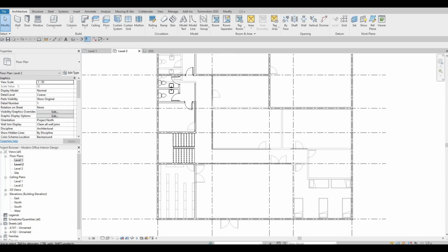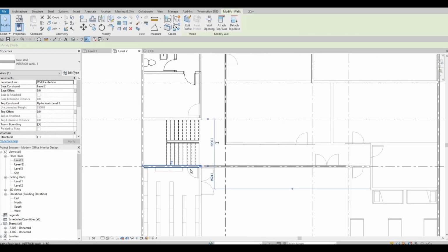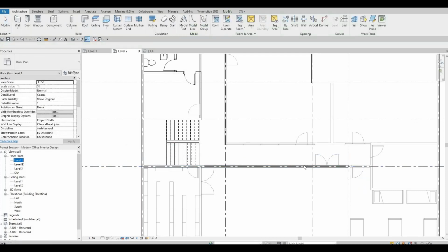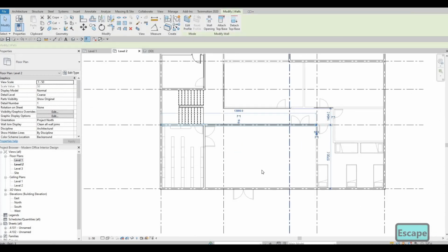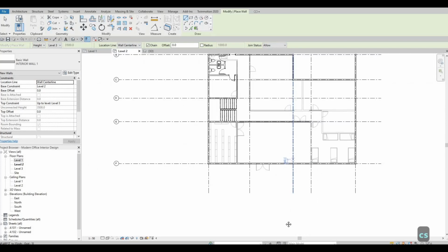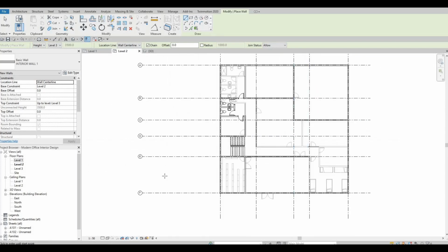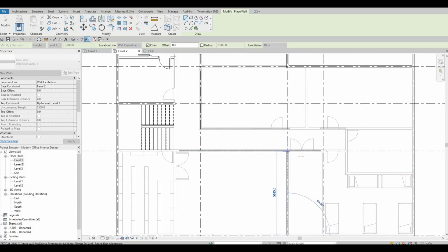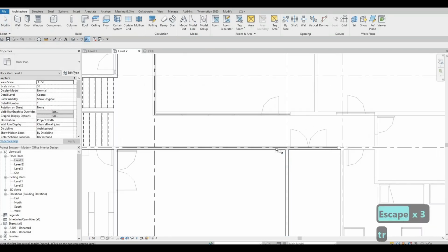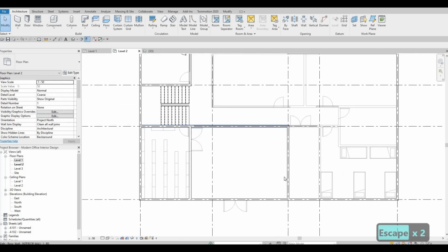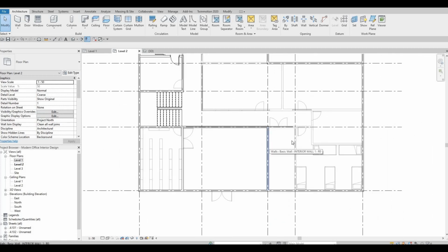Also, what we're going to do is select this interior wall, and I want to extend this all the way right here. So just extend that, select this interior wall again, CS. I want to click it from F3 going to E3, and then just trim and extend, or just trim this one. So now we extended our second floor like that.